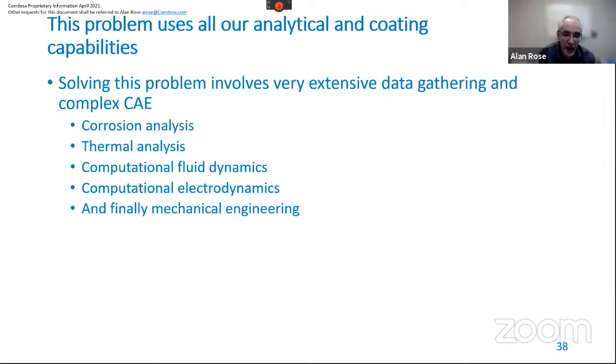Something to add with that system: we didn't show a photograph of it. The D2020 has the computer interface, and we track all the current that's actually delivered. So at the end of the process, you know exactly how much current was delivered over that time. Of course, current won't be delivered if you're going over a previously anodized surface.